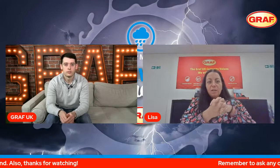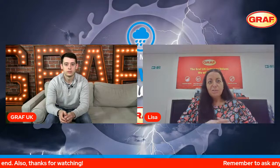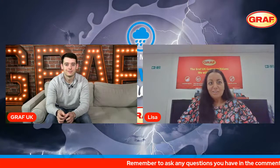We also do use a little heat gun for things like the adapter plates, because obviously they tend to be on the side of the tank, to seal the plastic together. But it's a specialist bit of equipment called a wedge welder that is the main thing, and we feel it gives the best welds, so much better than tape. That is a common way to put tanks together, and certainly other people do, but the welding just gives us, we say go for this guarantee because we're very, very confident in it, and the wedge welder is the best tool for the job.